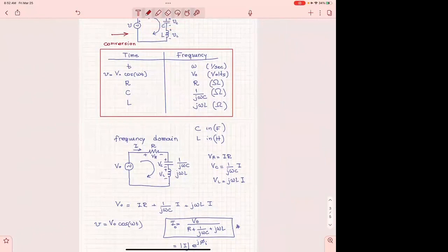Then Monday, we're going to start looking at three-dimensional structures and see how in a microstrip line, you use all of the information we got from statics to characterize it, to find a capacitance, and all the information we used from magnetostatics to find the inductance. Then we're going to use an RLC symbolic representation for the transmission line, and we'll start solving problems there. So that's how we're going to go. Any questions?